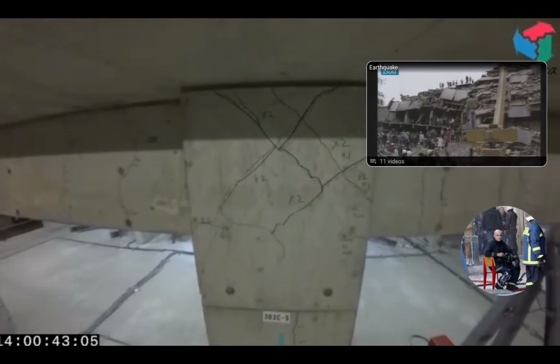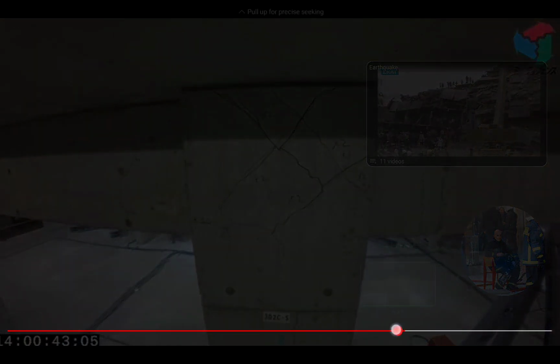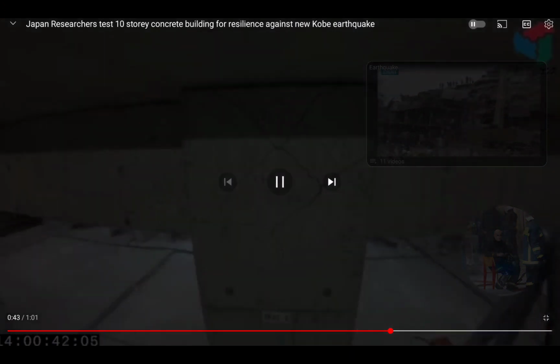As this shakes left and right, this gets a little more stable. This acts like a little compression test on this area here, and it fractures it and fractures it. And the more rotations, the more cycles it has, the more it starts compressing this area, fracturing it to hell. The top of this, well, it's not quite the head of the column, but there's the floor there, and that's where it's decided to pick on. Let's look at that again, the development of it.